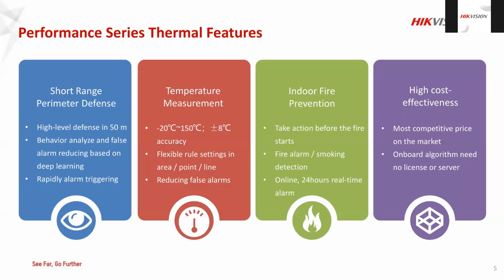The human body has some temperature, so we are also emitting IR radiation. These cameras can detect this kind of human behavior. The temperature camera can be used to detect it, and we can analyze whether it's a human, how it is moving, or how the movement is taking place. So definitely we can use temperature cameras for short range perimeter detection.